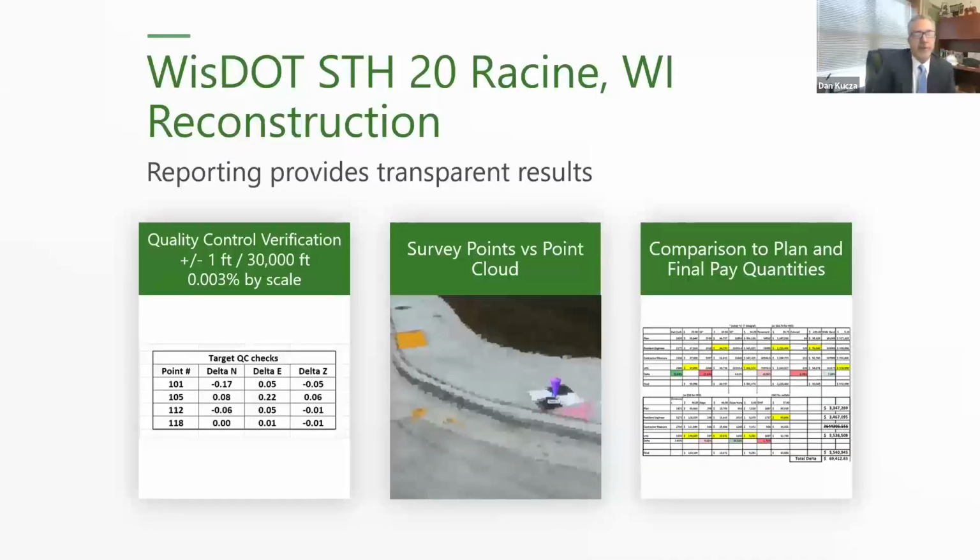So this is just showing some of the results. A lot of people ask right away, what type of results. We had 18 points across the project, which was about 1.25 miles. I staggered the points, and then I shot them with the GPS rover, which to me should get those points within a tenth of a foot.